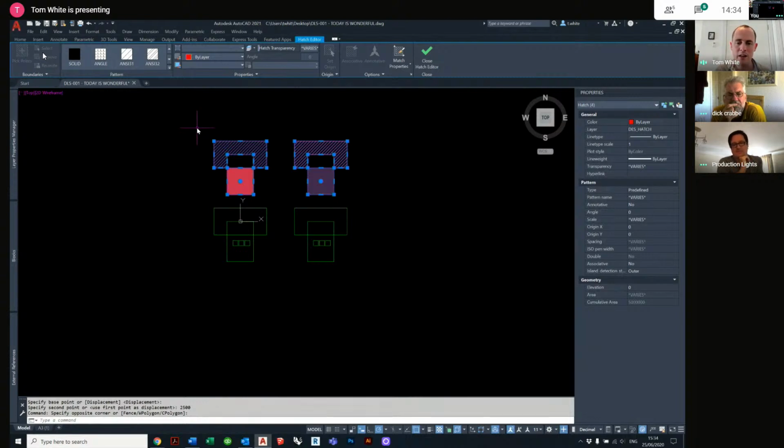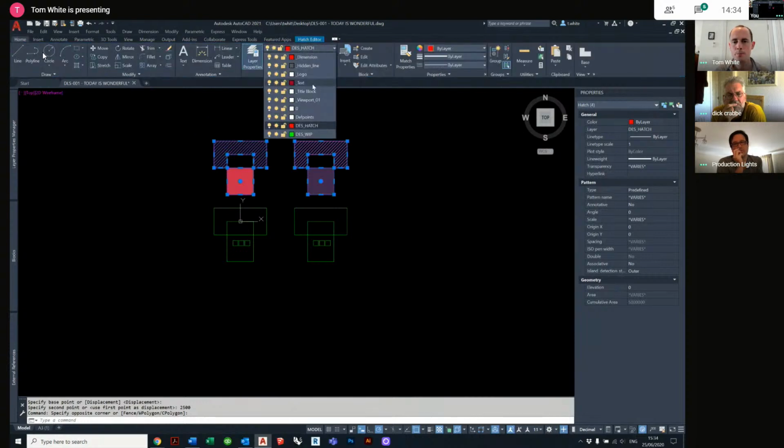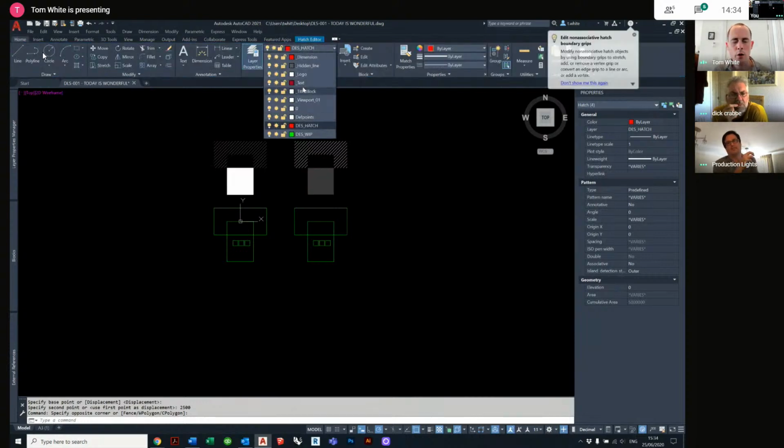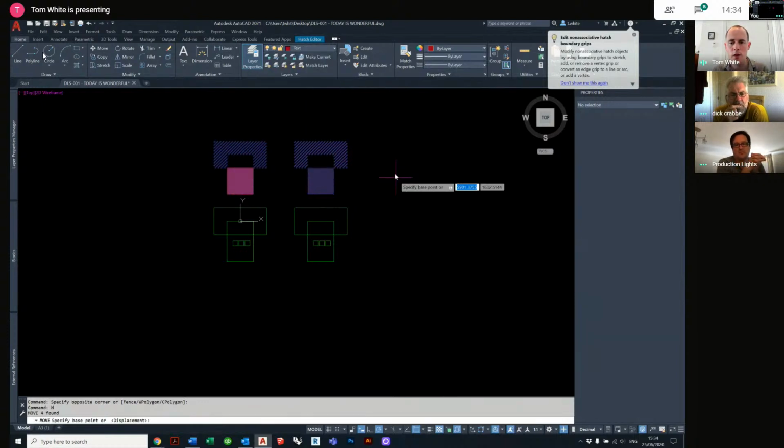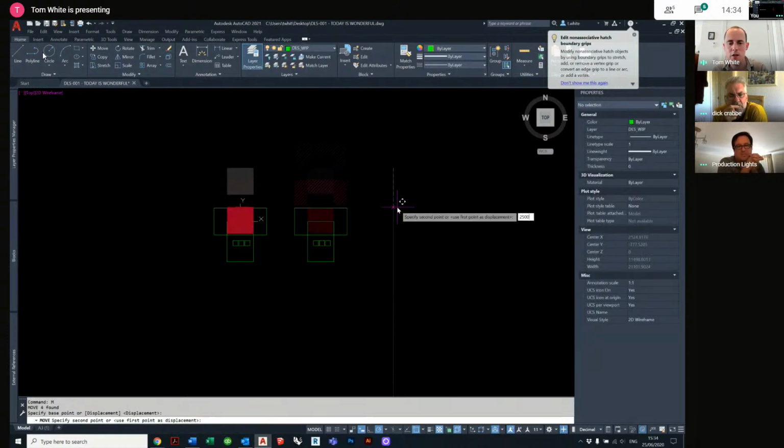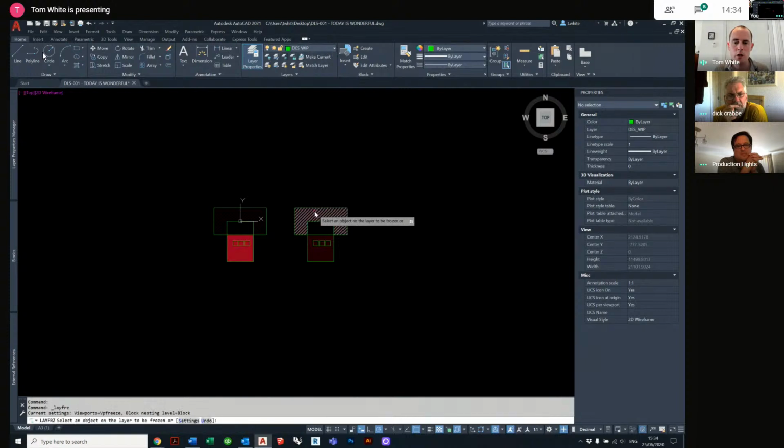And one way of improving in that circumstance specifically is you could change the layer of the hatch. So I don't have a layer set up, but you could do that, move it back by 2.5 meters, and then you could use the freeze command and freeze the hatch. And I think filter we haven't heard at all, doesn't ring any bells. Where does filter come in?